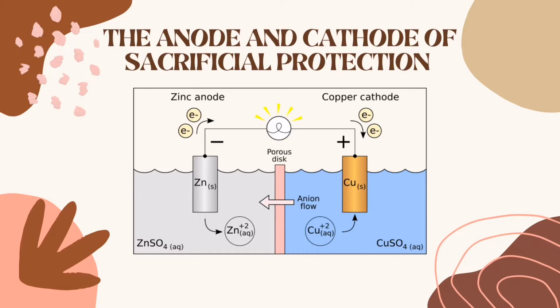Typically in sacrificial protection, a more reactive metal is used as a sacrificial anode by attaching it to steel pipes or pump bodies. The iron becomes a cathode which does not corrode, while the anode corrodes to provide the desired sacrificial protection. The sacrificial metal must however be replaced periodically as it is consumed, otherwise the protected metal starts corroding.